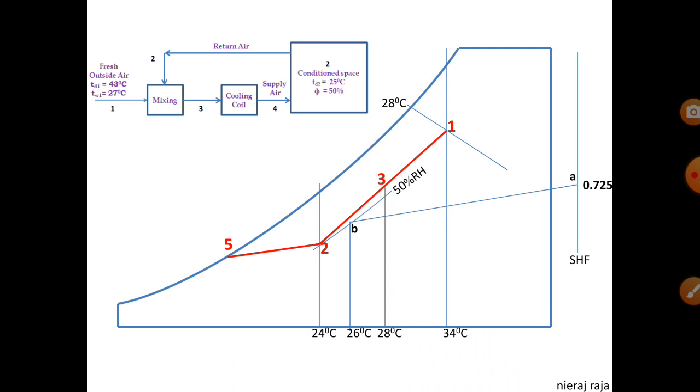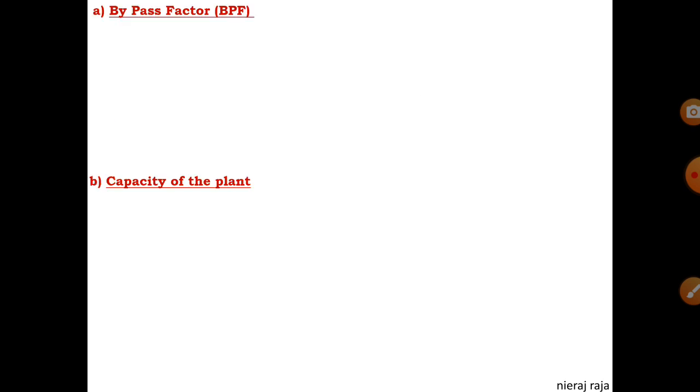trial and error method. तो उससे आपको मिलेगा TD6 और 6 से ज्वाइन करो 3, जहाँ पे इंटरसेक्ट करेगा पॉइंट, जो पॉइंट मिलेगा इंटरसेक्शन का 2 to 5 और 3 to 6 का, वहाँ रहेगा आपका पॉइंट नंबर 4। ओके, TD6 इज नथिंग बट योर ADP। अब जो फॉर्मूला आपने यूज़ किया दैट इज नथिंग बट दिस, bypass factor is equal to TD4 minus TD6 upon TD3 minus TD6।